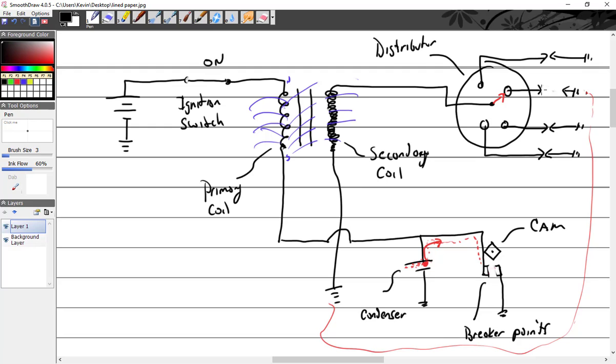And the voltage that the secondary produces is not purely, but in large part, dependent upon the gap that it has to jump. So not only is it the physical size of the gap, so I could use, like in the lab, points that I spread out 5, 6, 7, 8 millimeters more, but also if I just take something like this that's inside of a cylinder, the more air pressure I put in there, so PSI, the more PSI I put in here, the more voltage it's going to take.